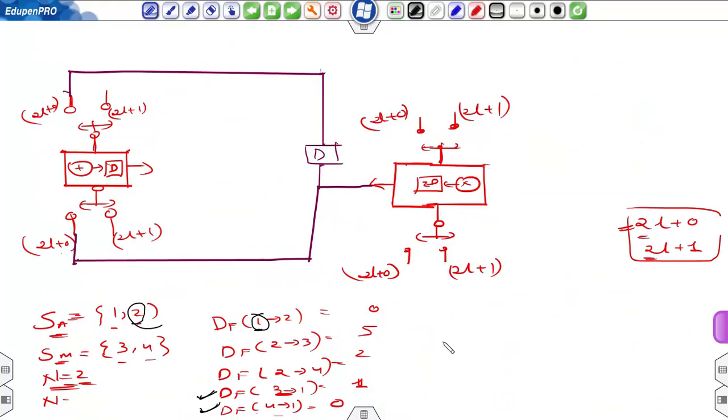Node 1 is an adder, meaning the output of the adder should be connected to its own input with 0 delay, and the second is the external source. So at this point I can provide the external source x(n), and the output of the adder is connected to its own input with 0 delay. So this completes the connection of the adder.